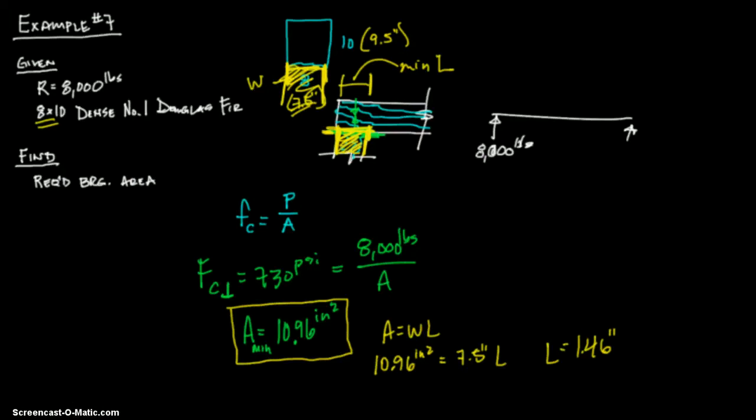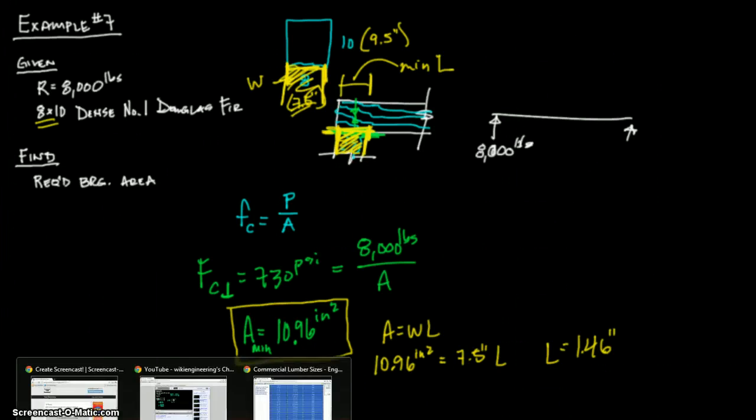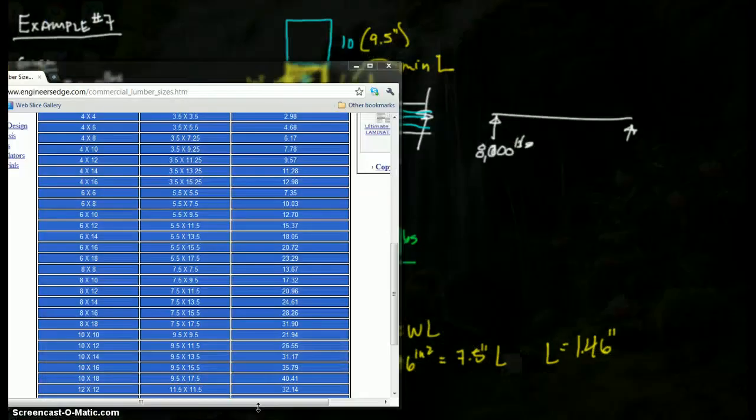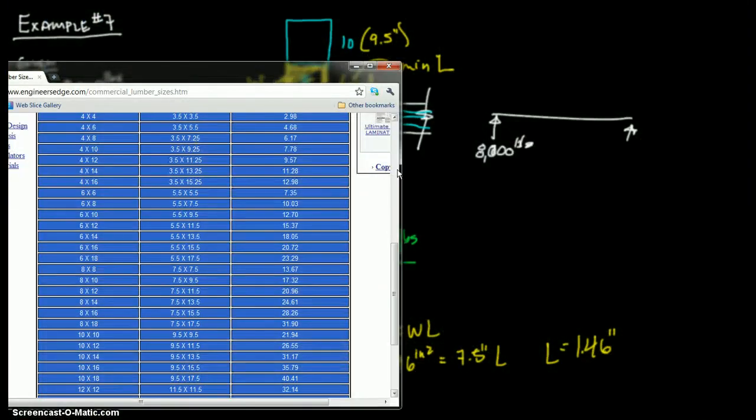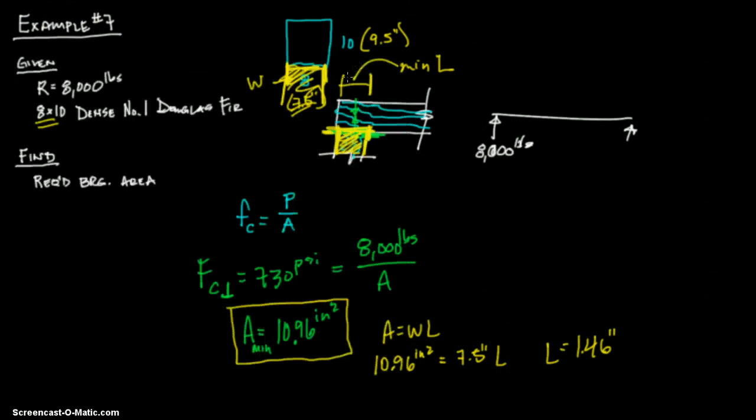Let's say a 4x4 post. In reality, you're probably not going to have any issues with this. A 4x4 is 3.5 times 3.5, looks like they're half an inch off each. 12.25. So the area equals 12.25 inches squared for a 4x4. So that's probably the minimum I'd specify.